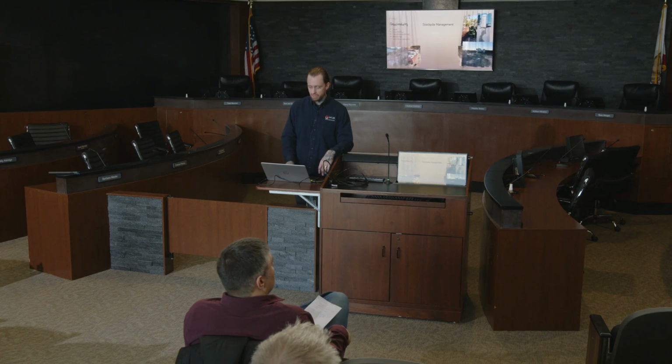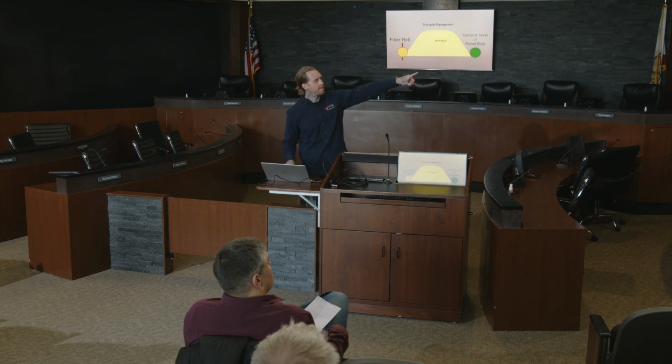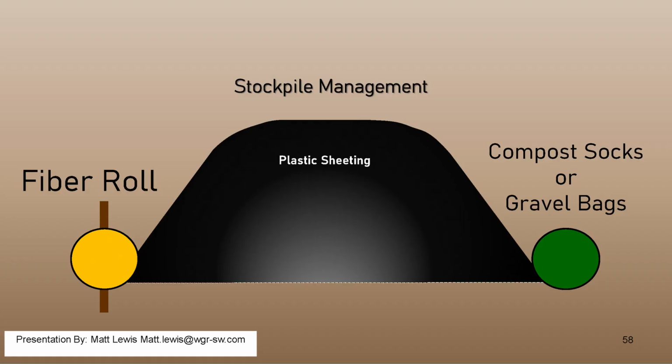All right, it looks like we're getting to a little bit of stockpile management here. As I had talked about before, you can see fiber rolls, it's kind of hard to tell with this graphic. It's not the greatest, I apologize. But a fiber roll should be keyed in, a little trench, 3 to 4 inches, keyed in, laid in, and staked down. But when it comes to compost socks, or gravel bags, they're self-weighting and you don't need to do it. But the idea with the stockpile, having it bermed, is because usually the standard thing is putting plastic over the top. But when you put plastic over the top, you create accelerated velocity. And so usually it's on dirt, the stockpile.